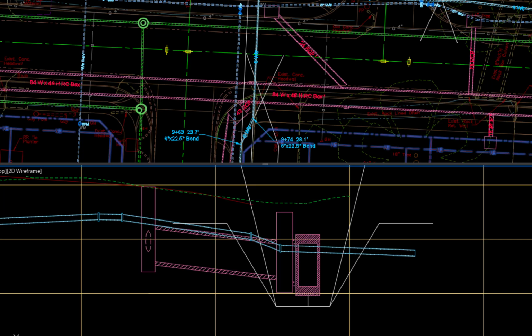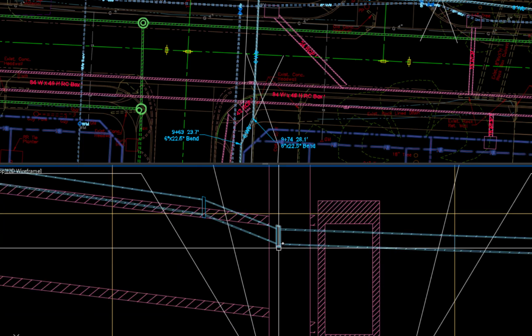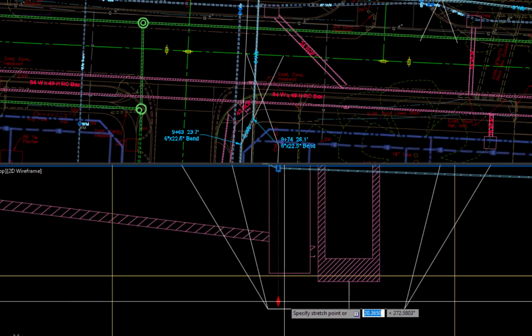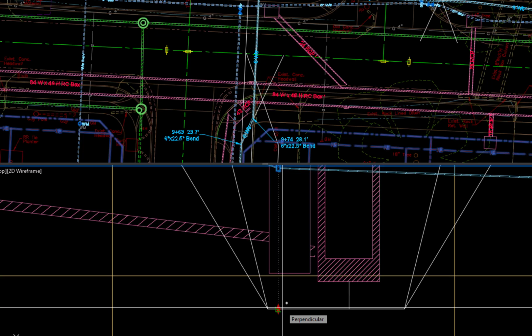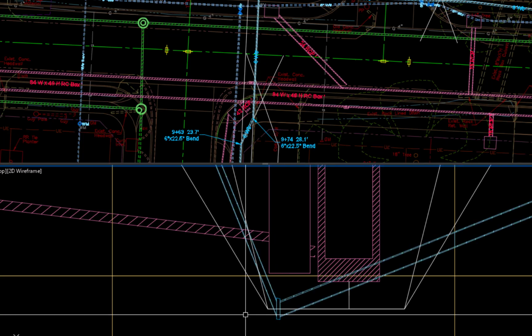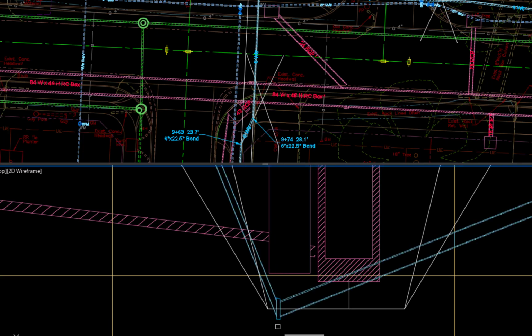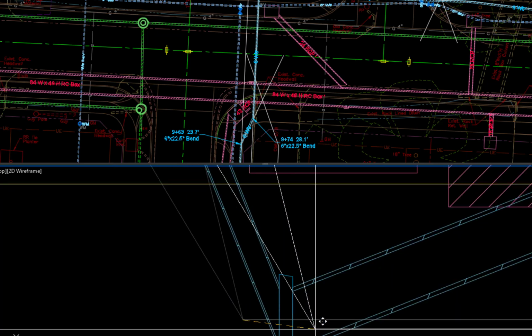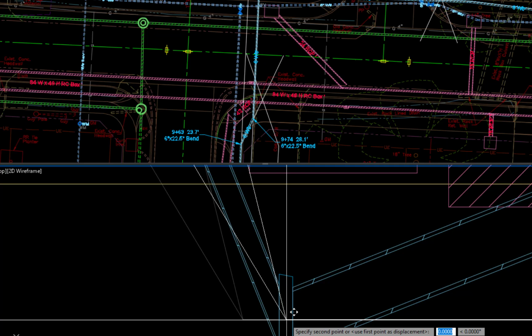In order for the pipe to be within available right-of-way, the horizontal bend at 9+74 needs to remain at the horizontal alignment location shown. Pick the bend in the profile, pick the center glyph, and move vertically to intersect the horizontal template line. Escape. Enter to start the move command. Pick the bend template, pick the angle point, and move horizontally to the center of the bend.